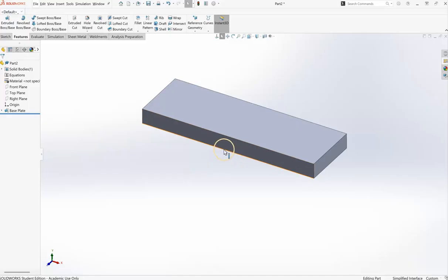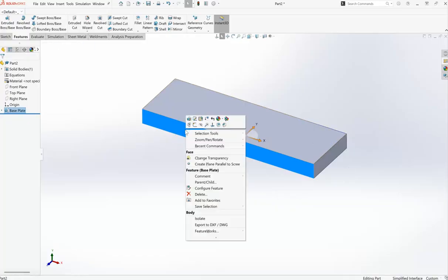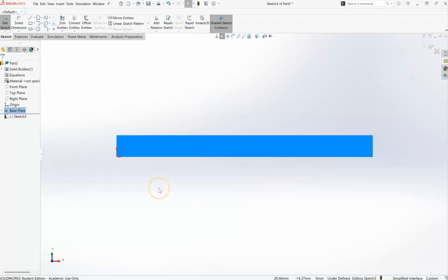But so we're going to click on this front surface here, and when you do, we can do this in two different ways. I'm going to click on that, and then here I'm going to select sketch. The other way I can do it is I can right click and I can select sketch. And so what happens is when we initiate this new sketch, it's going to turn normal to you so we can see it, and we're basically looking straight at it.